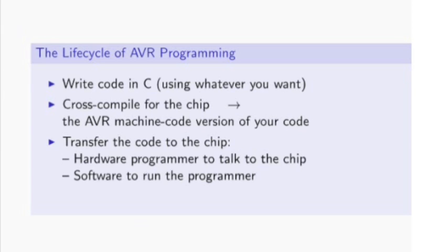And so this is something that translates to the AVR chip. On your computer side, on your laptop side, you're going to need software to run this programmer. So software to speak to the programmer, and then programmer to speak to the AVR in SPI to get it programmed. Once you program it over, you get feedback and debug until it works, just like usual.